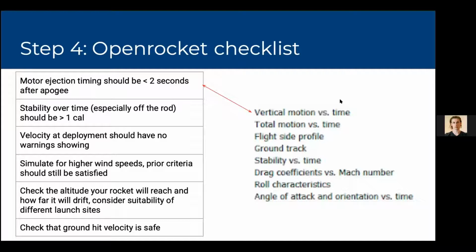Yeah, that would be the best way to check the overall trajectory of your flight and make sure that your motor is ejecting at the right time, and not ejecting too early, when your rocket is still moving and the parachute gets pulled apart, or too late, and it crashes into the ground.